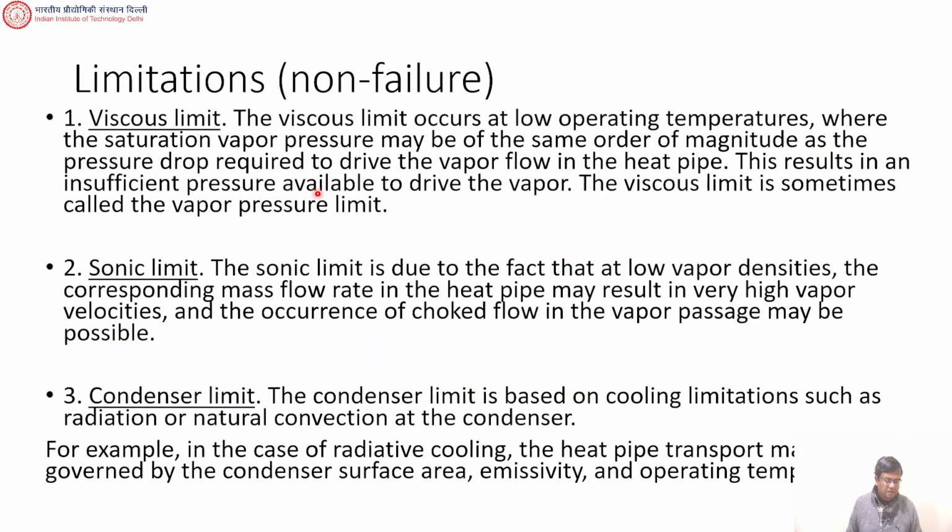So there are some viscous limits. The viscous limit occurs at low operating temperature, where the saturation vapor pressure may be of the same order of magnitude as the pressure drop required to drive the vapor flow.